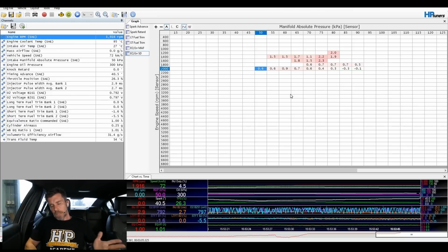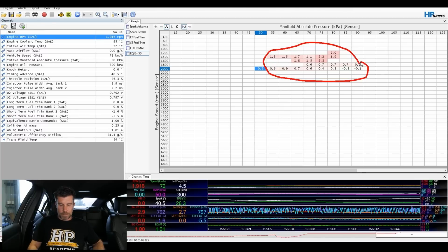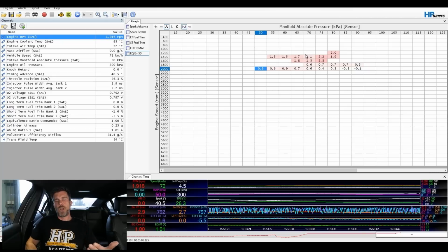So first of all, again, notwithstanding the fact that we are in closed loop mode, we can see that these numbers would all be pretty happy with that. Generally, if we're within about plus or minus 2 or 3%, I'm pretty happy with the calibration, and that's exactly where we are. No surprises there with our closed loop active, but we want to know what the numbers actually mean and whether we can trust them here.